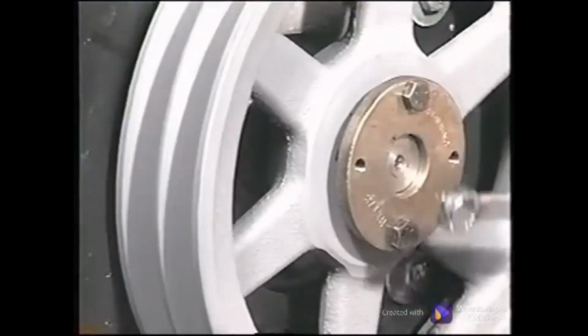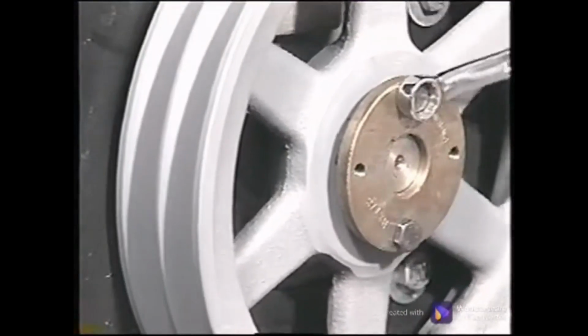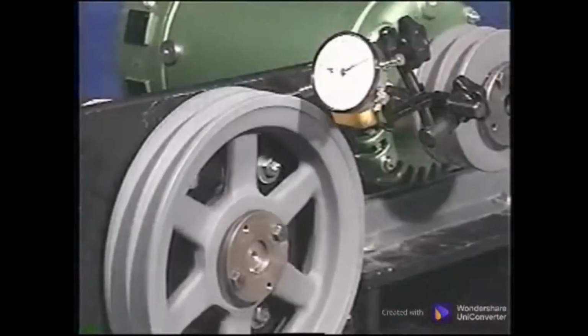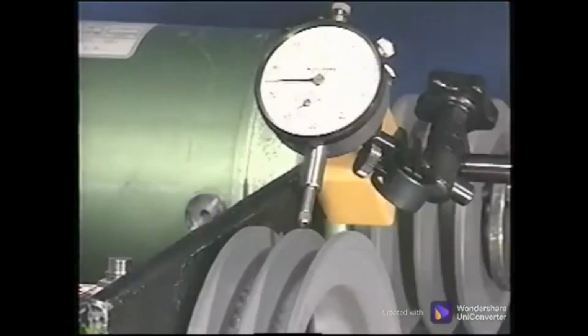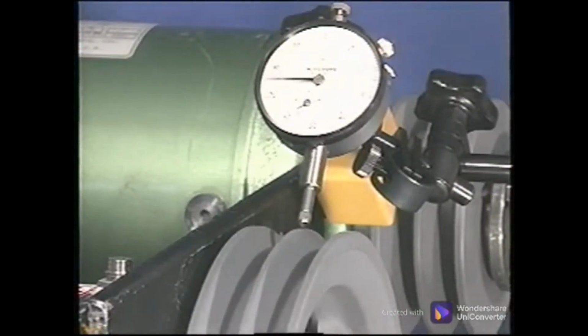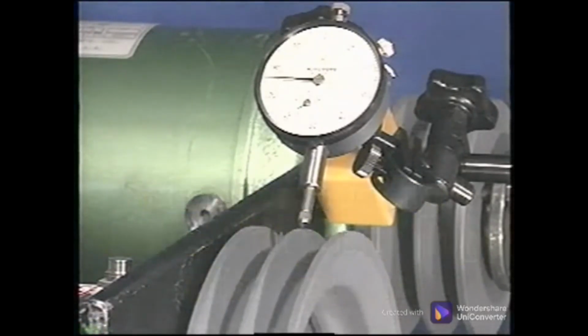The face is usually not machined and may not be parallel with the groove walls. Tighten the bolts a little at a time so that one side does not pull in more than another, causing runout. Check the groove walls again to ensure the sheave is square with the shaft. Now the sheave can be checked for radial runout or eccentricity. This should be checked before the final positioning of the motor. If the sheave is eccentric, it is better to know that now than after the final positioning. Now the belts can be installed and the final alignment can be performed.